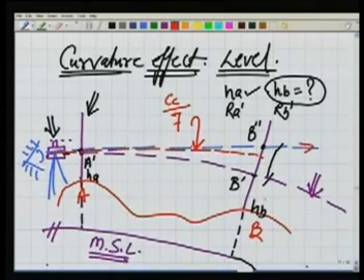If we apply the same logic, what exactly are we looking at? In my instrument, we are looking at a point in my staff which is B triple dash, a point here. So, what will be the correction now? I would like to apply the corrections. First, take this point up where my horizontal line should have bisected, then this point down to B dash where my level surface should have bisected.